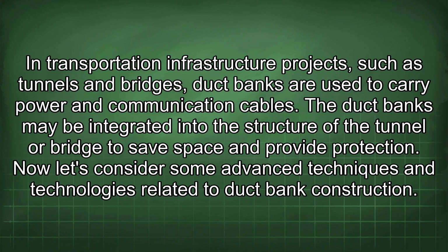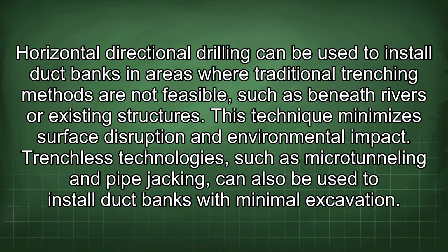Now let's consider some advanced techniques and technologies related to duct bank construction. Horizontal directional drilling can be used to install duct banks in areas where traditional trenching methods are not feasible, such as beneath rivers or existing structures. This technique minimizes surface disruption and environmental impact.